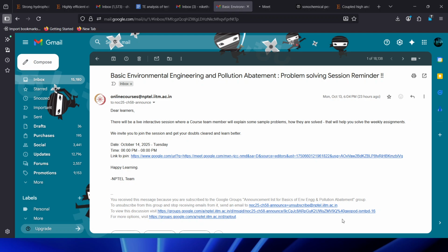different pollutants, which are PM10, PM2.5, NO2, SO2, carbon monoxide, ozone, ammonia, and lead. Even if only 3 pollutants' concentrations are present, the data can be calculated. But one of them should strictly be PM10 or PM2.5. The other one can be any of these gases.